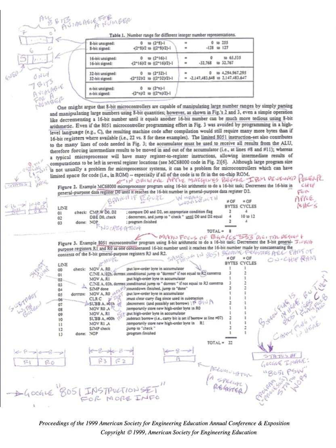But here we're comparing the Motorola microprocessor in the first example to the Intel microcontroller. You can tell just by looking at it that there are a lot more lines of code with the microcontroller. But if you look at the number of cycles it takes, it takes longer for the microcontroller, even though you have these more powerful instructions.